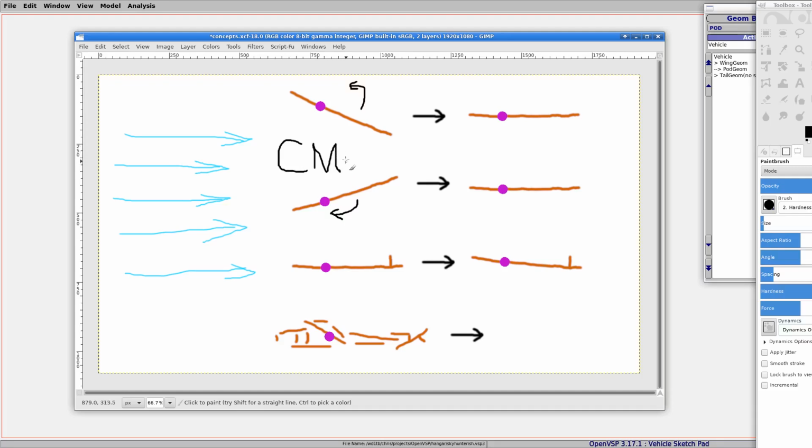And again, it's a coefficient, so it's not a real world measurement like foot-pounds of torque or anything like that. It's just a magnitude, and it's called CMY in the graphs. So just remember that this is a force or a torque turning it one way or the other. And when it gets to this point, because it's now perfectly in line with the wind, we wouldn't really have any coefficient of, well, it'll be 0, right? So let's just say that the CMY equals 0 at that point.